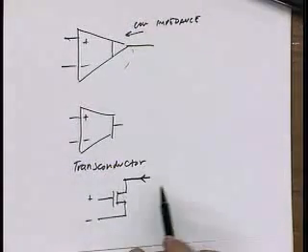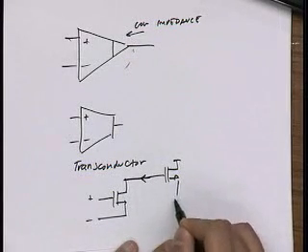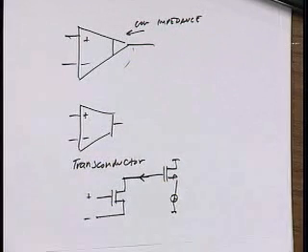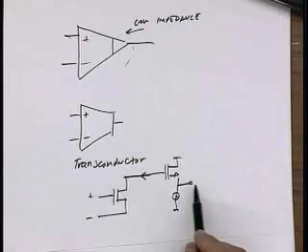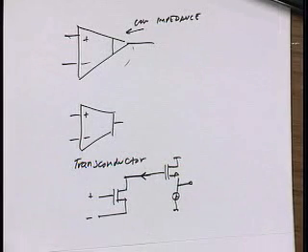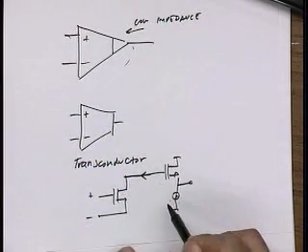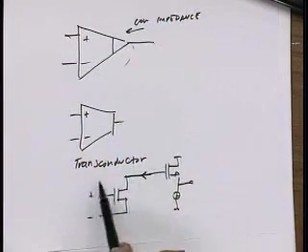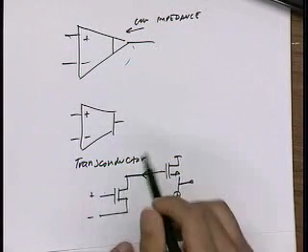So to turn a transistor into an op-amp, we need an output stage. And maybe we use a source follower or something, right? So now I have the world's cheapest op-amp. This is my output stage. It's pretty low impedance if I run enough current through this. Okay. An OTA, I don't need this output stage, right? Because an OTA is a transconductance amplifier. And so the output impedance is actually high impedance.